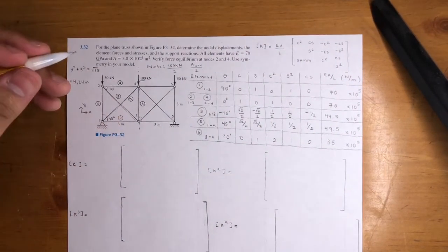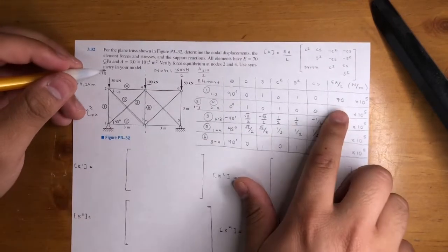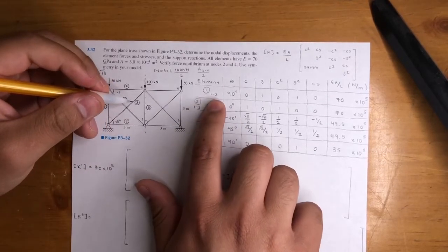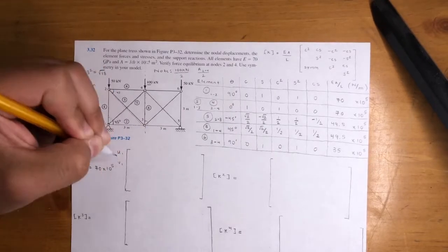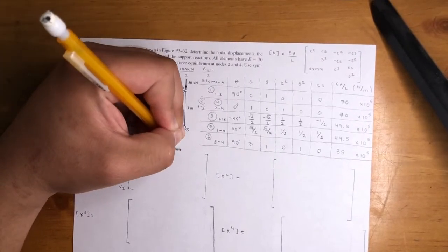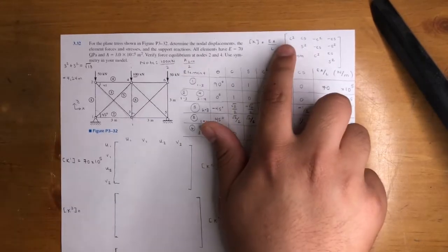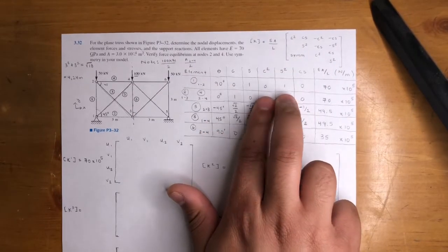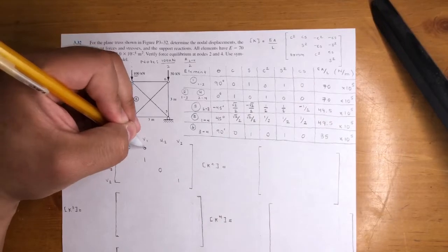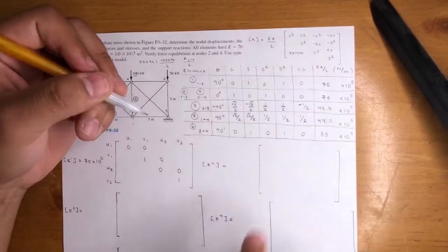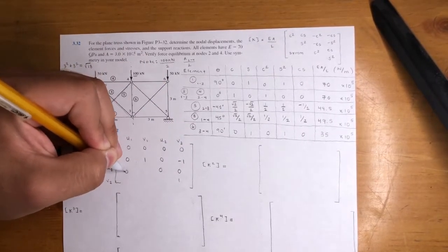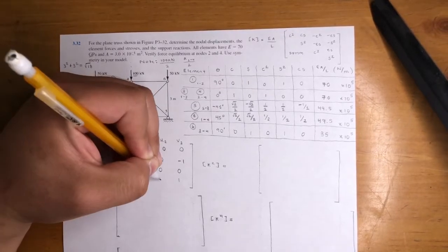Okay, cool. So we could go ahead and start filling in the matrices, right? For element 1, we get the EA over L, 70 times 10 to the 5th. And that goes from 1 to 2, okay? So it's U1, V1, U2, V2. Same thing here, U1, V1, U2, V2. And that's going to be cosine squared, sine squared, cosine squared, sine squared. So we'll get these two numbers, 0 and 1. So it's going to be 0, 1, 0, 1. Cosine times sine is 0, 0, 0, 0. I'm just using this matrix. That's going to be a 0 up here. It's 0, negative 1. Symmetrical, so the rows become columns. 0, 0, negative 1, and 0.